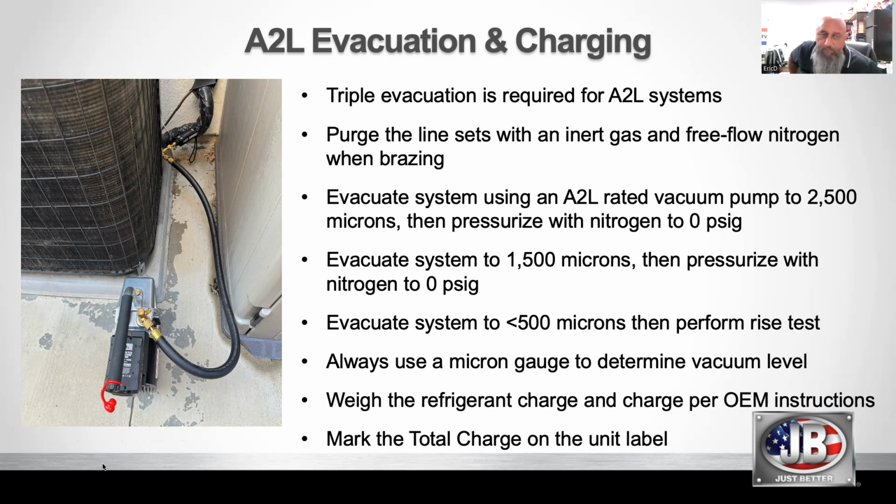3 times is there's a lot more work required, and if you're a tech out there who is using a 1/4-inch hose and you're not pulling your Schrader cores, now's the time to move to a bigger hose and pull a Schrader core through a valve core removal tool, because it's going to save you a ton of time when you're doing all these multiple evacuations to get your system ready for charging.